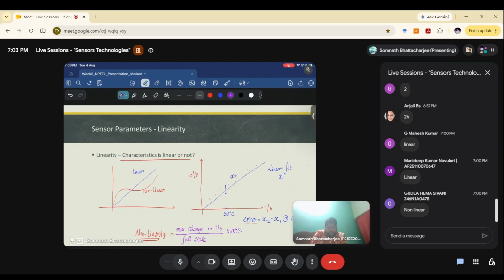But by changing this, you can control this behavior, and utilizing that you can make a memory. When VGS is getting towards a higher point, that is the zeroth state, because no memory is stored there. But when VGS is coming back from a higher value, that is -5 to +5, it gets to a state that is called the one state. So this one is a one state and this is called a zero state. So thus a non-volatile memory OFET, or a non-volatile memory transistor, is being made now.